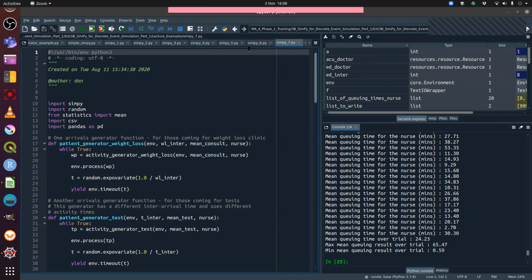Sorry, just on top of that, is it going to crash the CSV if it's getting days of simulation, or is it generally okay? No, you should be fine. What you don't want to do is be in a situation where you're exporting out to Excel files, because yes, you will very quickly run into that. You can have incredibly large CSV files with no issue.